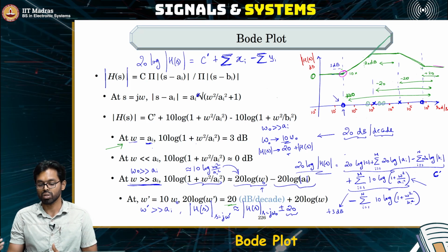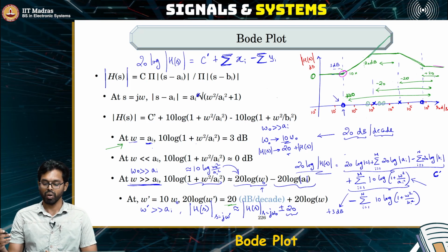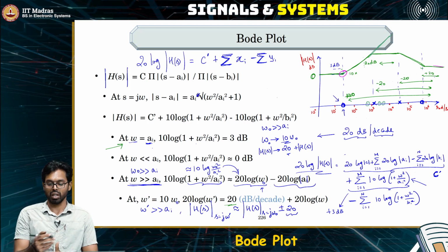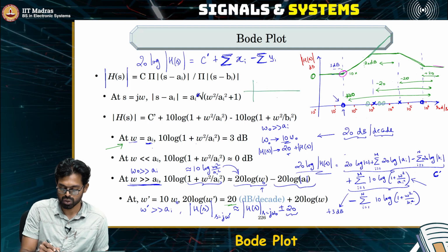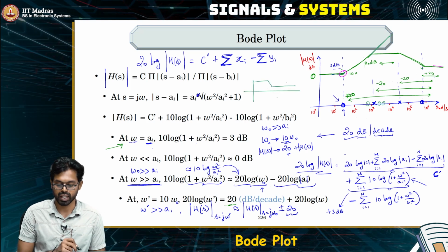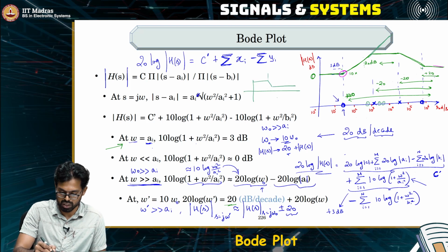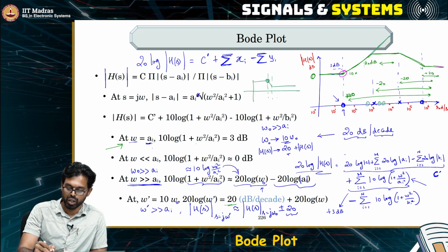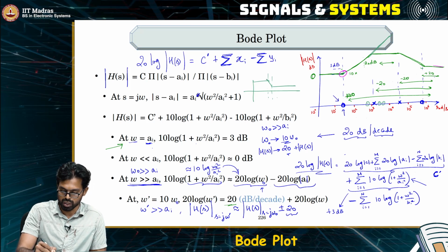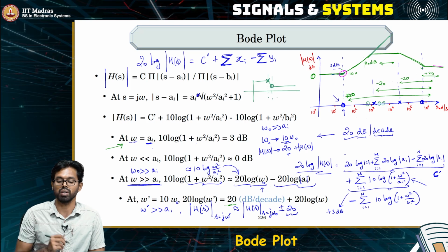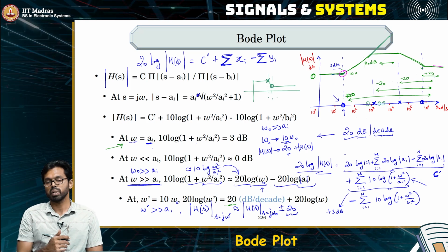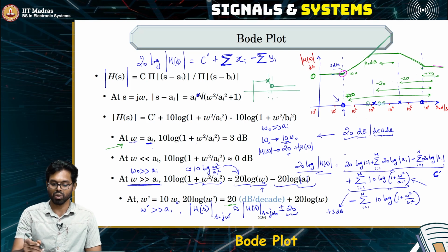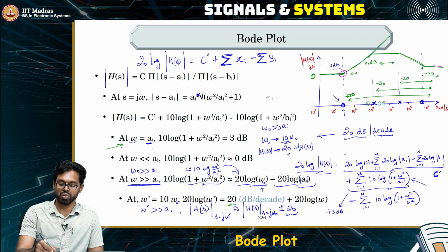So this tells you what to do, how to construct a filter where you should have a pole or a 0 such that you would get the frequency response that you desire. Now if I say that I should have a frequency response something like this, then clearly just by knowing what your requirement is, it is also telling you where you should have a pole or a 0. So there should be a pole here and there should be a 0 here. So just by knowing your requirement, you will know what should be the pole 0 locations, and once you know the pole 0 location, you can construct this transfer function back from that.